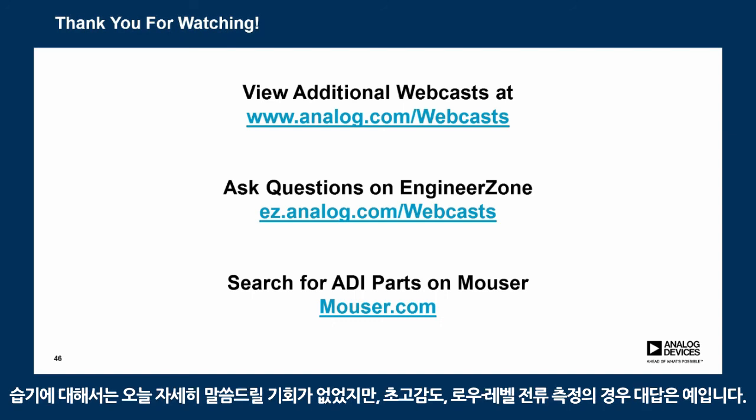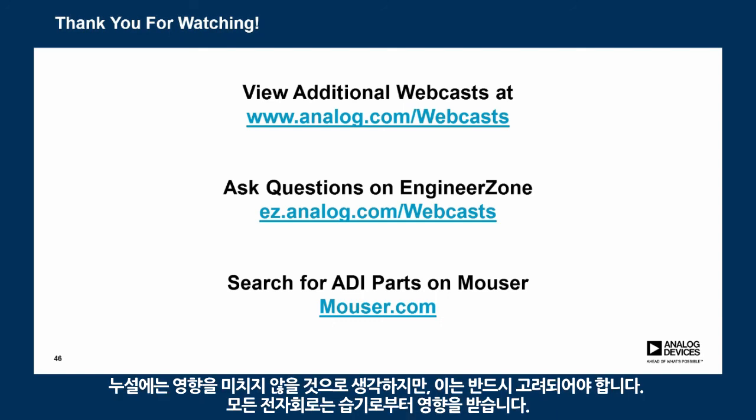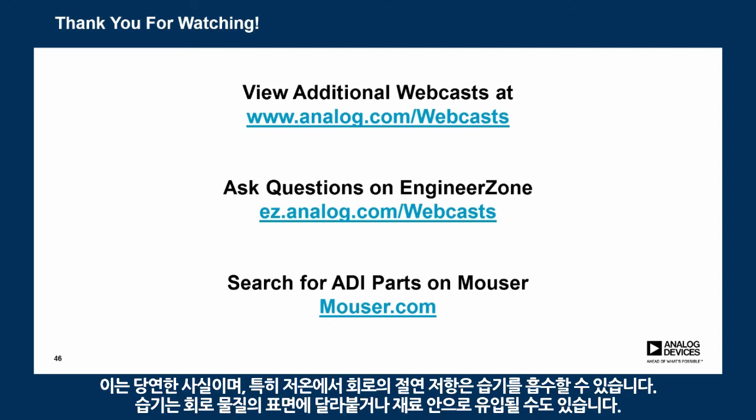Humidity is something that I didn't really have a chance to talk about in this webcast. But short answer, yes. For ultra high sensitivity, low level current measurement, every little thing could contribute to leakage and has to be considered. All electrometer circuits are subject to humidity effects. This is very true, especially at low temperature.